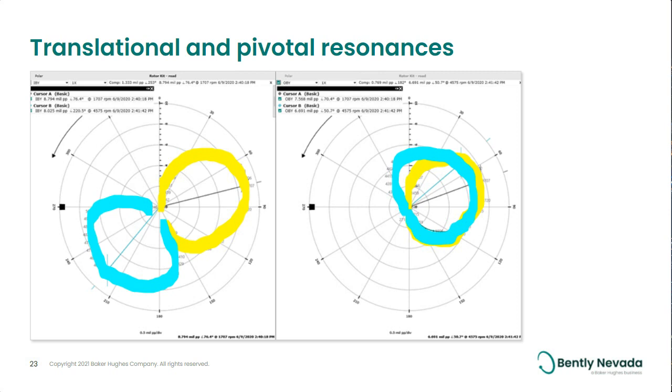So our first mode heavy spot is right up at the top, like top dead center on both ends. And that makes sense, right? And then the second mode heavy spots are slightly off, 180 degrees from each other between the inboard and the outboard, but you'll see that on the outboard, they're still within 45 degrees of each other.